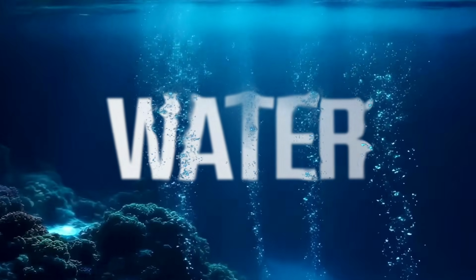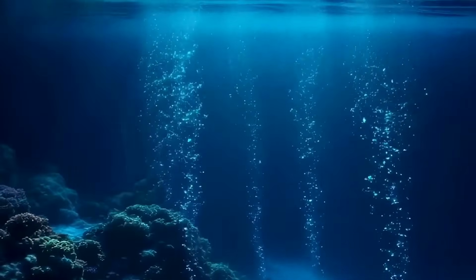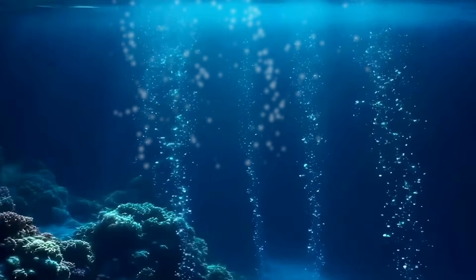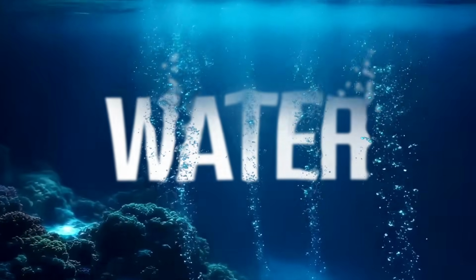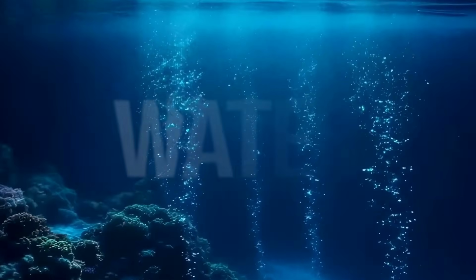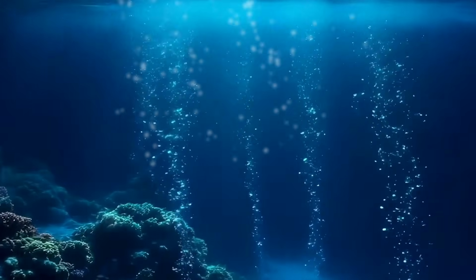Hi guys, today we're going to be doing this animation. First things first, obviously we're going to need a text plus node, the text. We'll notice that the bubbles kind of deform the text, so it means we're going to need a displace node. Then the footage itself is just imported footage, so we import the footage in, and that should basically be what we will need to do this animation.